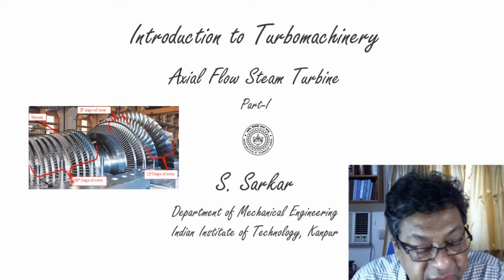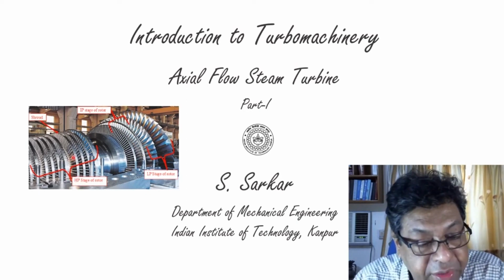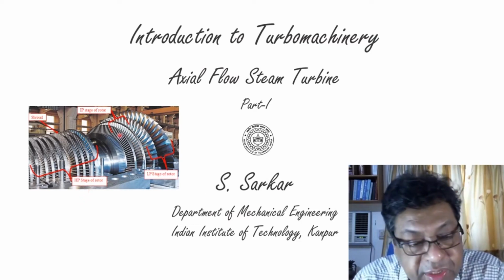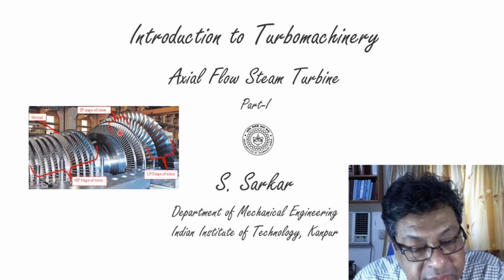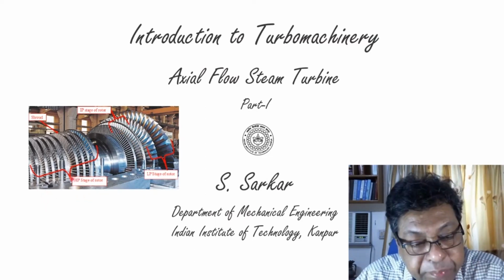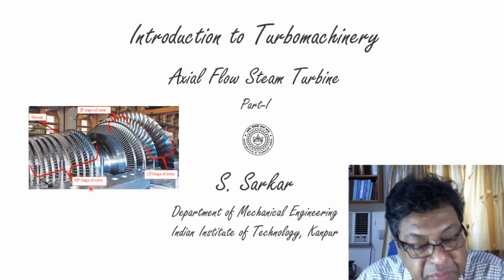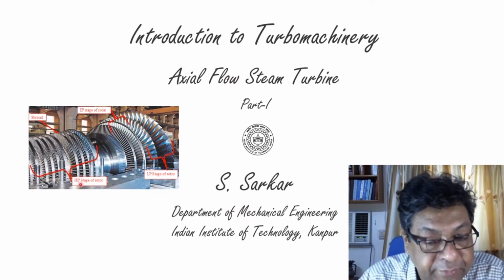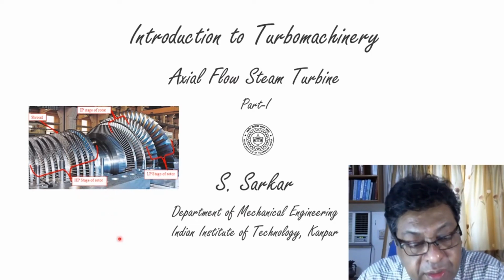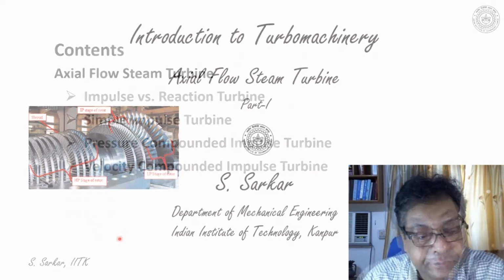In the HP section, blades are mounted between the hub and the shroud, and the blade height is also considerably low as compared to the LP section. Hope you would appreciate the construction of a real multi-stage steam turbine. With this introduction, I'll present now the steam turbine.